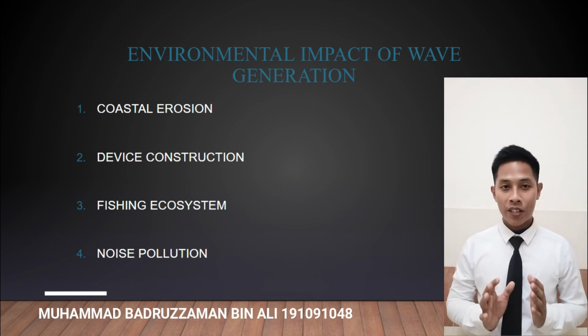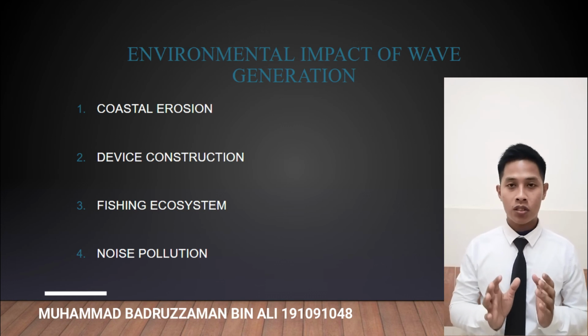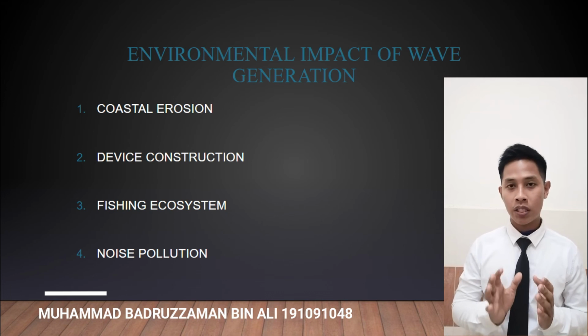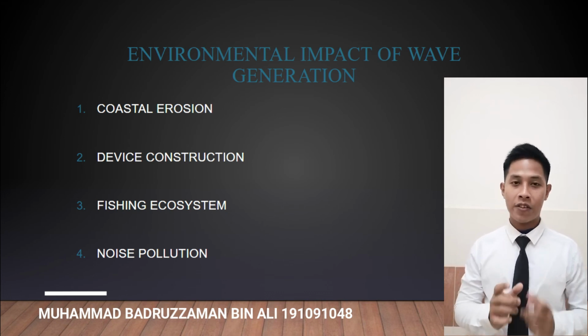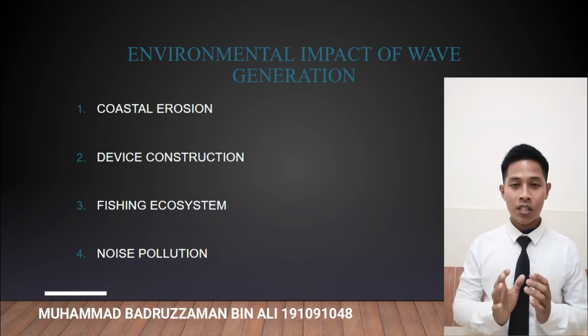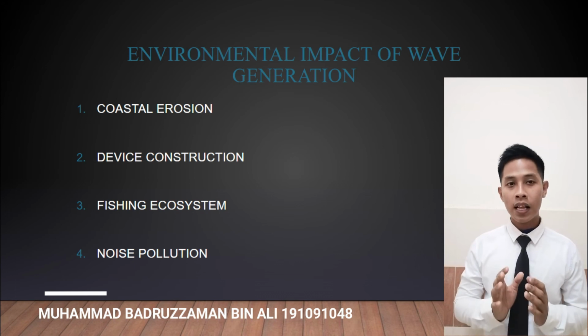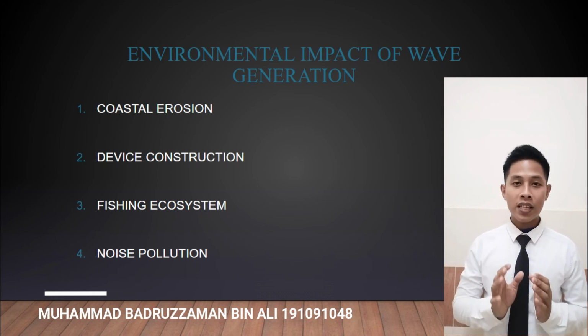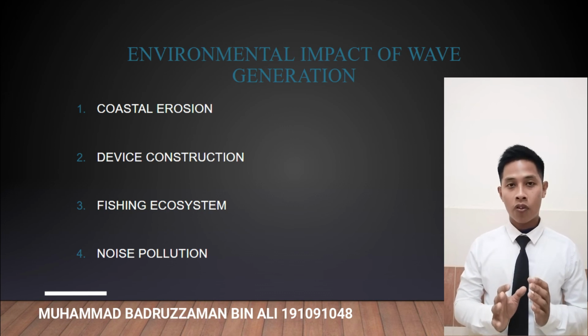The second one, device construction. Anchoring these devices may have an impact during installation. Piling, concrete blocks, anchors and chains are used to secure many tidal and wave energy devices to the ocean floor. Dredging and scouring of the seabed may be required for site preparation in order to install electrical cable. The number of devices installed and the mooring system used will determine the amount of ocean bottom disturbance.